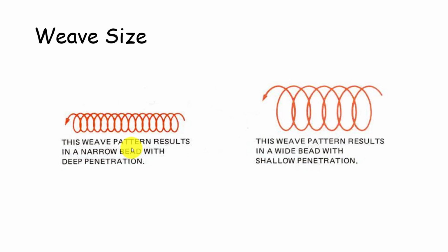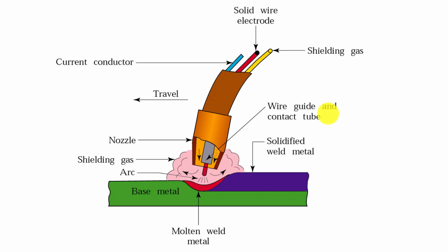And I just put a simple weave pattern on here, where sometimes they just do an elliptical type shape, and maybe it's a little tight and a little bit looser, and that's going to change the depth of the penetration, how the welds tie in, and all that. And they're going to be watching those welds, seeing what happens.